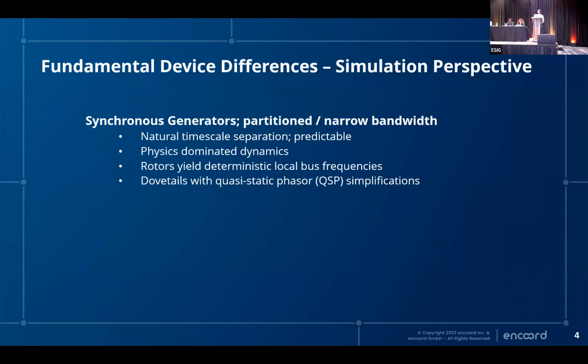And this works really, really well with the contemporary approach for dynamics, which is colloquially known as phasor domain. I like to think of it as quasi-static phasor, QSP: PSSE, PSLF, PowerFactory. Those sorts of tools do this phasor domain analysis, right? Which works really well with synchronous generators.